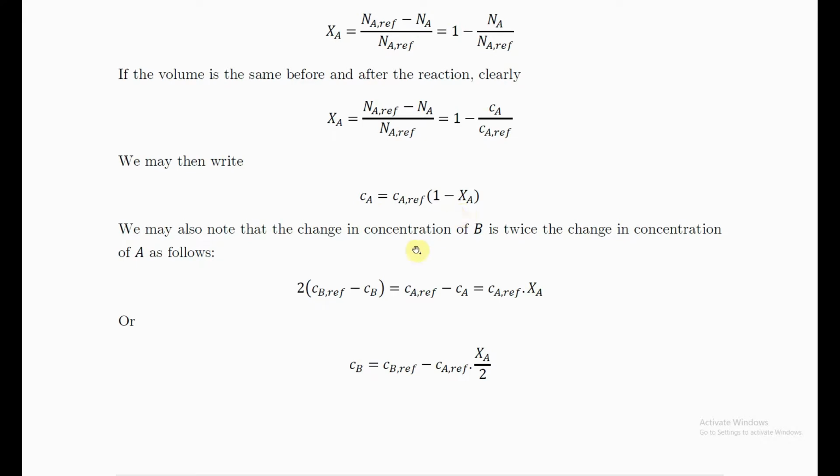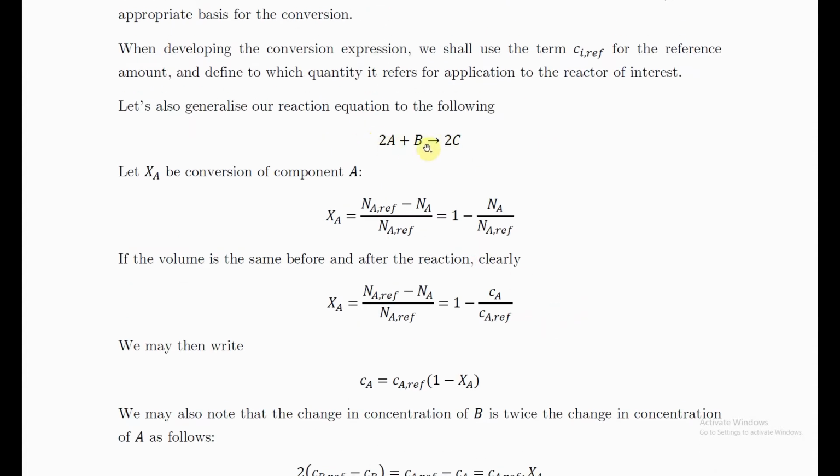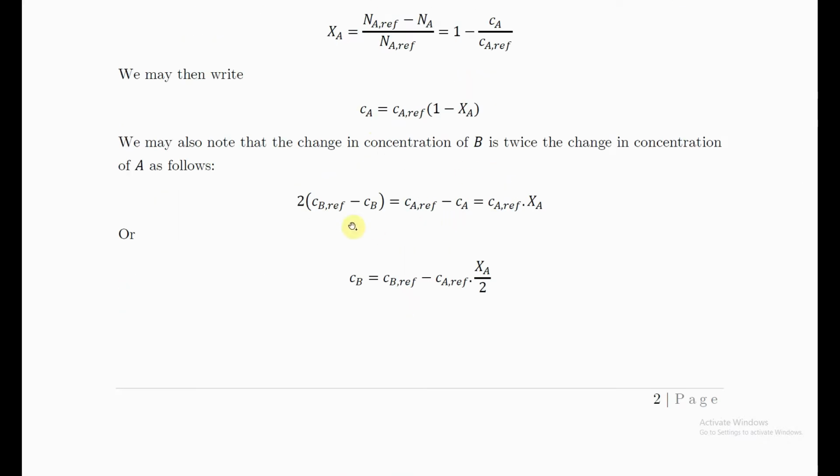And then we can think about our reactor, if we just think about component A and B reacting, and we are talking now specifically about this, we can see that, as we said already, twice as much of A being converted is equal to the amount of B that's converted. So the amount of B that's converted, we can say, is the initial or inlet amount subtracted from the amount that's currently there. So the initial amount minus the current amount, that must be the amount that was converted.